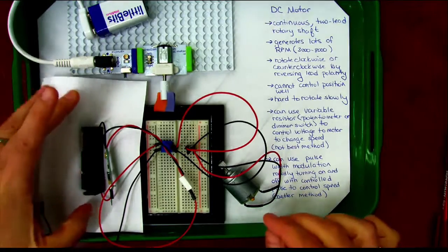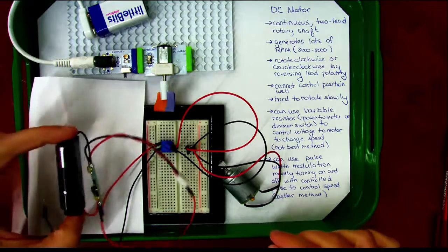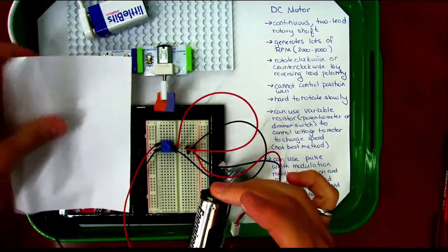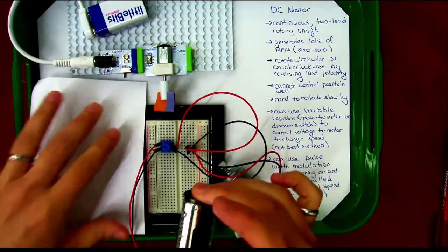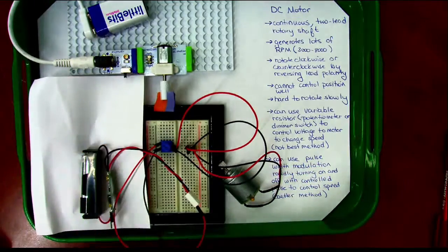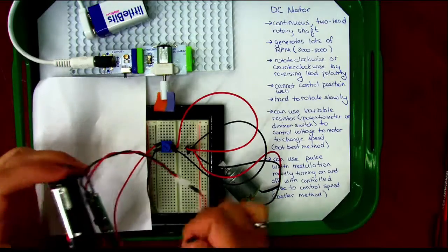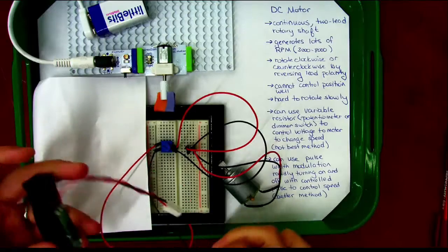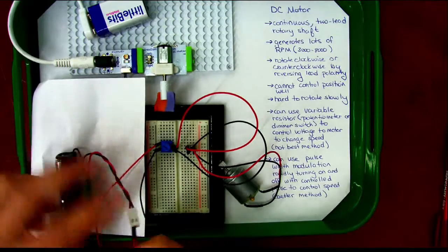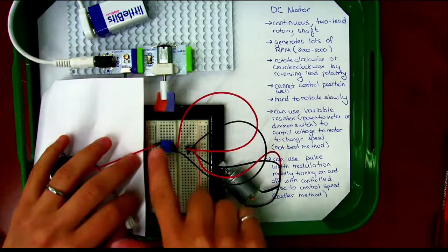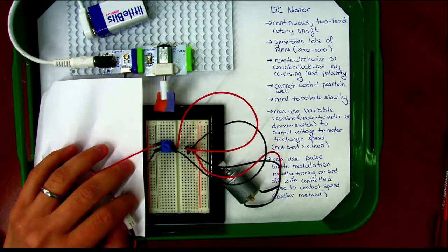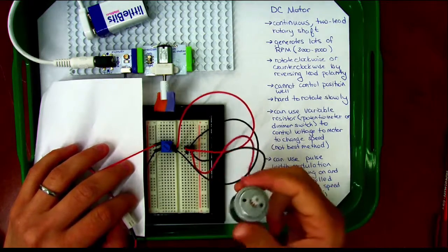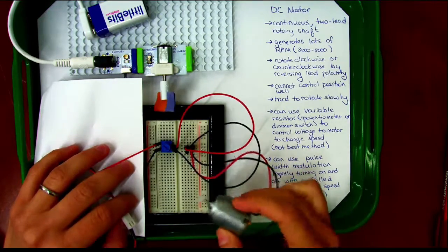So, DC motor, I brought a couple for you guys here. This one, I covered up the board because I'm not actually using the SparkFun program, but this was already stuck down, so pay no attention to the stuff under the paper. I just got a battery, and it has a little circuit to bring it up to 5 volts that it's delivering out to 2 wires. I put my potentiometer in the middle so we can control the speed by reducing that 5 volts down to some proportion that then goes out to our little DC motor here.